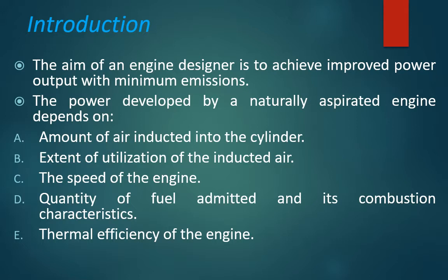But prior to that, we will learn what the need for this is. The aim of an engine designer is to achieve improved power output with minimum emissions. That would be the primary aim of an engine designer. The power developed by a naturally aspirated engine usually depends upon the amount of air inducted into the cylinder, the extent of utilization of the induced air, the speed of the engine, the quantity of fuel admitted and its combustion characteristics, and finally the thermal efficiency of the engine. So in order to increase the power, we have to work on all these 5 parameters.